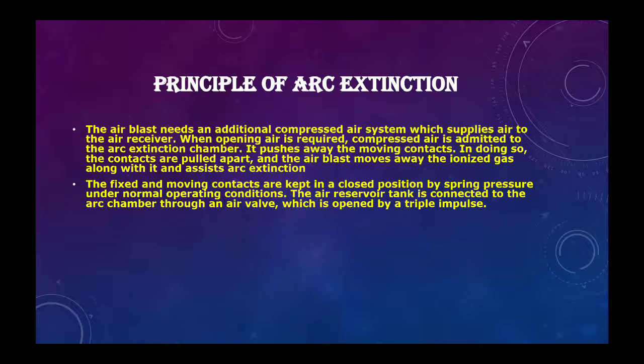The fixed and moving contacts are kept in a closed position by spring pressure under normal operating condition. The air reservoir tank is connected to the arc chamber through an air valve, which is opened by a tripping impulse.